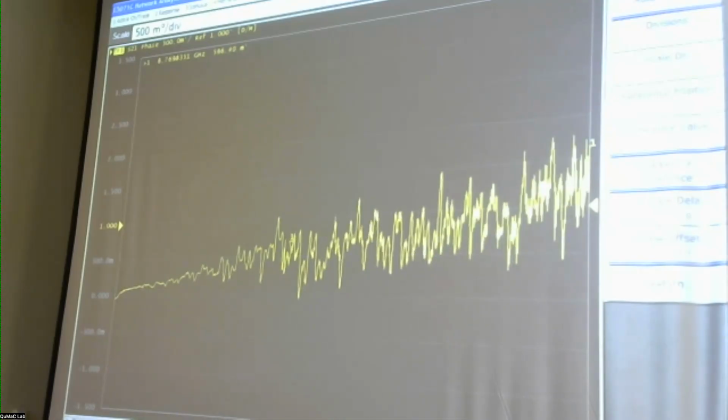Right? If something left as sine omega t or sine theta here, then when it reaches the other end, it's going to be theta plus omega delta t, but delta t is the time of travel from one end to the other end. That is now plotted as a phase out here. So this cable is, I think, about 9 inches or something. Yeah, no, this is a 12 inch cable. So it's giving you a phase accumulation of about 1 degree from 0 to 20 gigahertz.